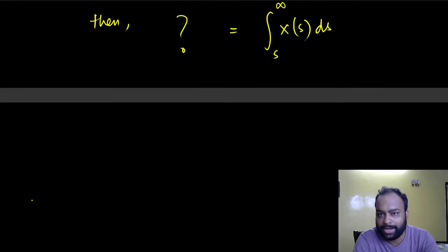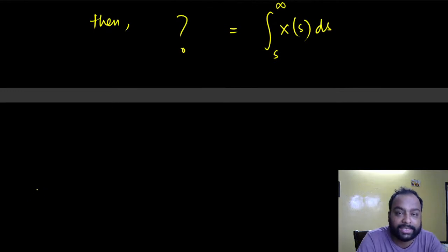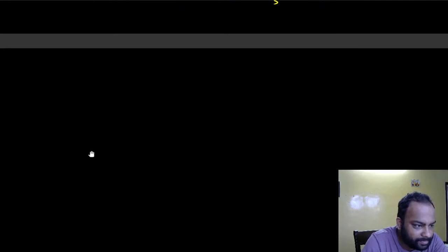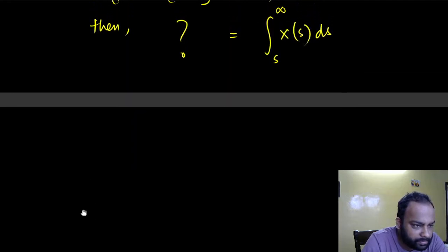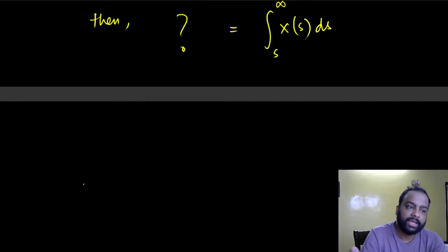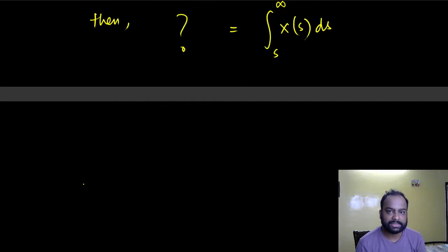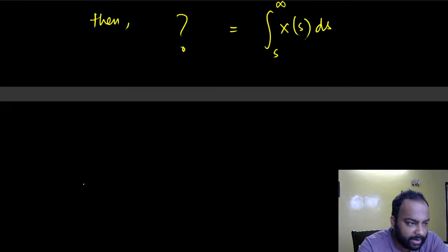Now, how would that be, right? And these things are taught in your digital signal processing classes. And just one more thing, we are discussing continuous time signals and systems. If you are talking about discrete time, also digital, signals and systems, in that case the Laplace transform essentially changes to something called the Z transform, the equivalent of the Laplace transform, and the Fourier transform still remains a Fourier transform, only a discrete or digital version of that.